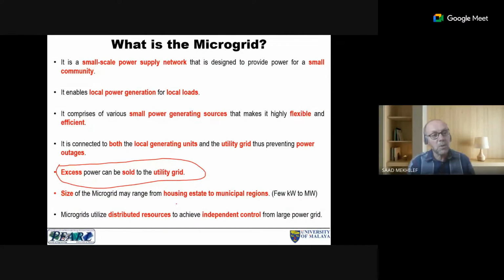No, picogrid means talking about something less than 5 kilowatts. Nanogrid, you're talking about less than 10 kilowatts. Microgrid, you're talking about a few kilowatts and above. And the operating voltage, it depends. We can operate at 48 volts. We can operate at 120 volts, you know. But if DC, most of them, we operate at either 48 volts or 96 volts.